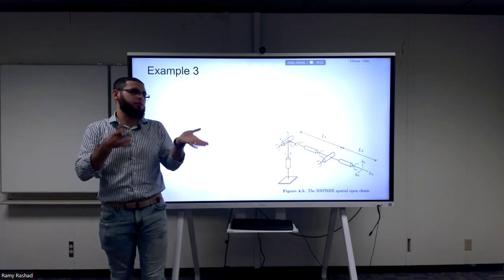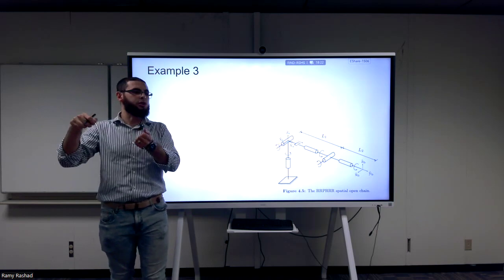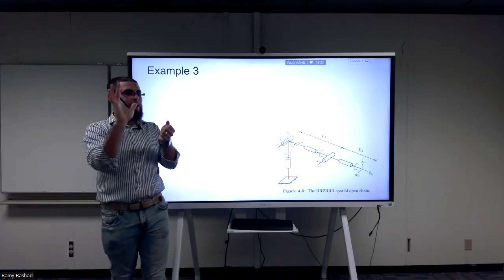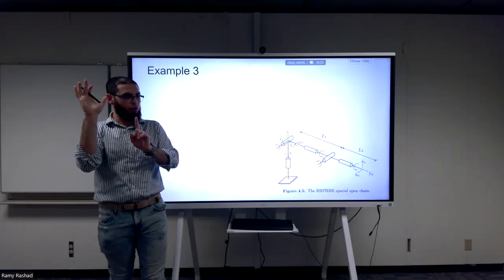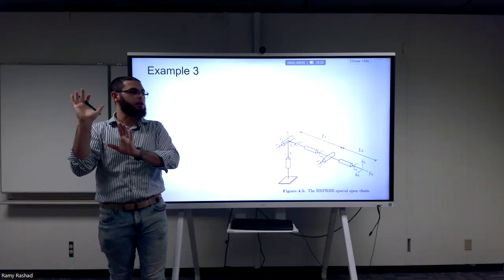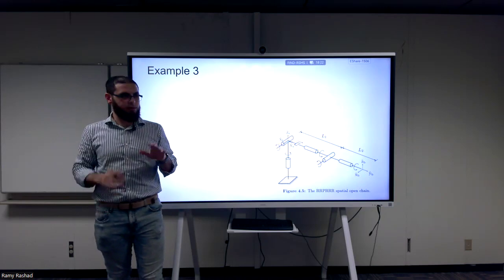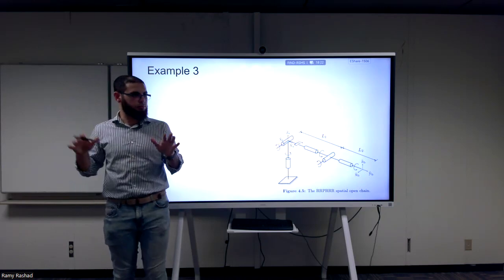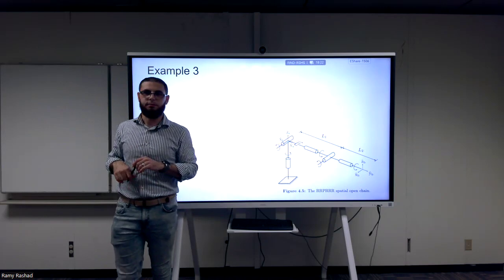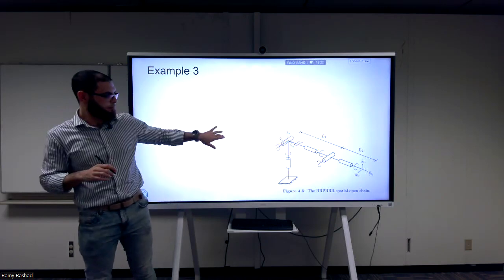Usually one easy fix is to put limit switches, so that when the robot goes back to these joint locations, this is the 0 position. And then you can always start from there. This is one way of doing it. Again, a basic way. Of course, different companies would do it in different ways. Any questions?